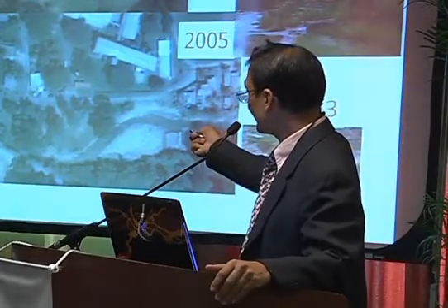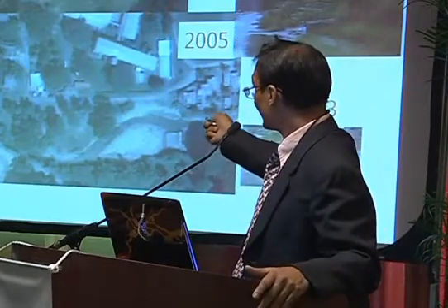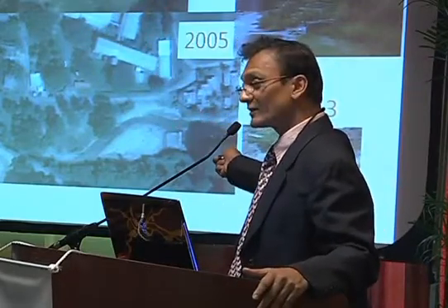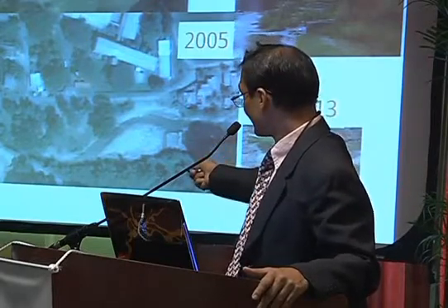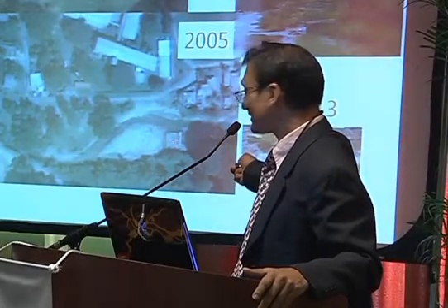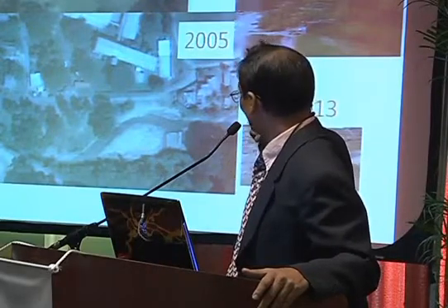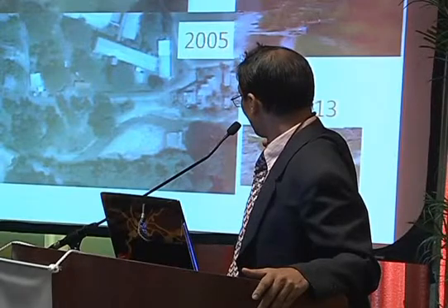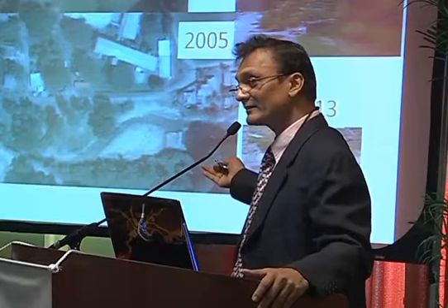So by diverting the river past the collapsed structure, you had this increased gradient, and flood events, now experiencing the steep gradient, caused the erosion of the bank and the loss of the water supply. And this is 2005, and the bridge works is continuing. This was the apron of the weir in 1997. This is the top of the apron, and this you will see is the present bed level.